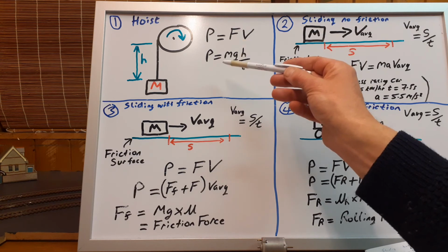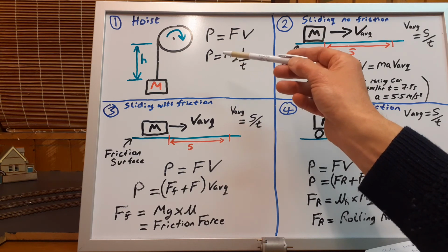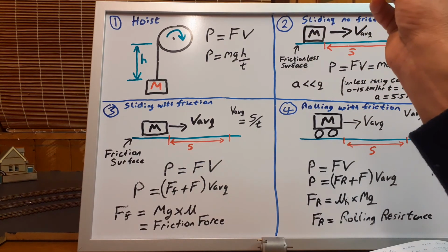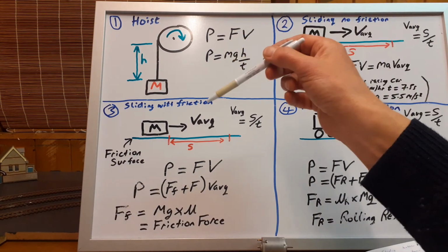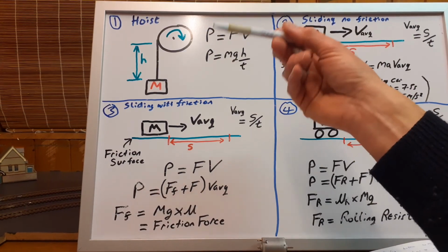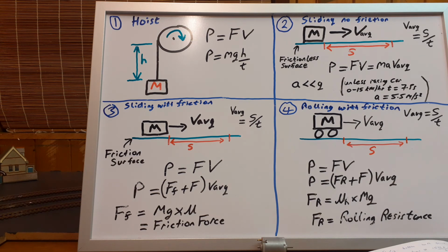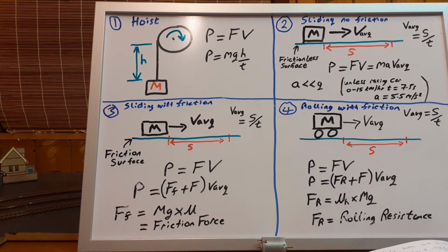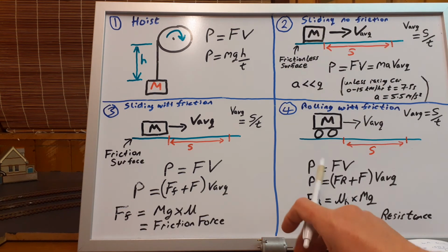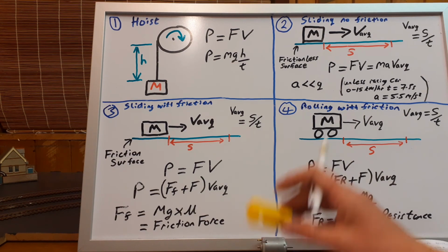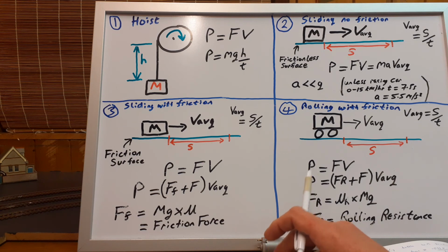And get it from a reliable source, or make sure the motor has a proper spec sheet that gives you voltage, current, torque outputs, speeds, etc. The best type of motor actually is one which gives you a torque versus speed chart. So at different speeds, it's going to give different torques. So again, be wary. Do your research before you buy. And maybe if it's too cheap, maybe it is too cheap.